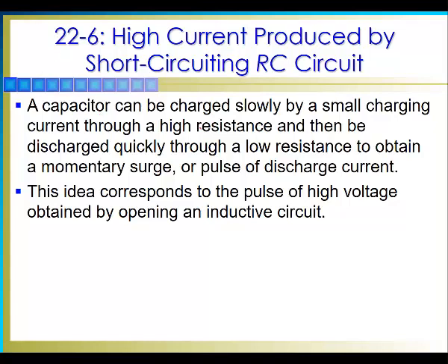So a capacitor can be charged slowly by a small charging current through a high resistance, and then be discharged quickly through a low resistance to obtain a momentary surge or pulse of discharge current.